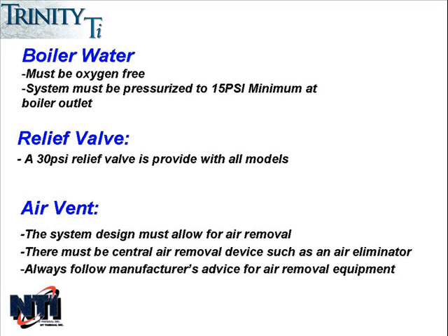Hot water boilers are designed to operate with airless water in the system, so an air elimination device of some sort needs to be installed in the system to remove air from the water as it circulates through. It's recommended to include an air eliminator on the secondary system as well.